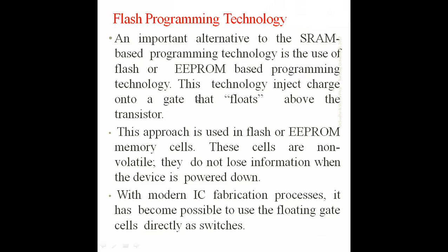This technology injects a charge into a gate that floats above the transistor. This approach is used in the flash or EEPROM memory cell. These cells are non-volatile. They do not lose information when the device is powered down.